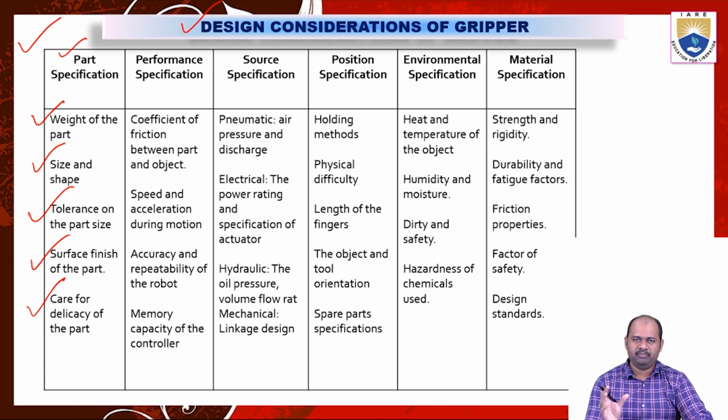Anyway, I have to apply some pressure by using the mechanical grippers. The two fingers of the mechanical gripper should be held tightly towards the object. So the force applied by these two fingers should not be enough to break the objects.